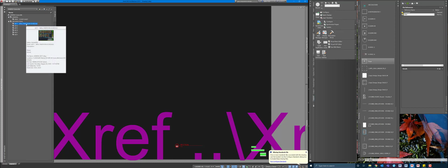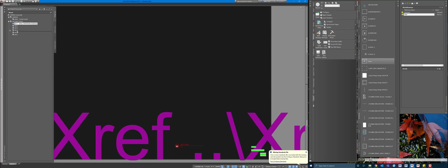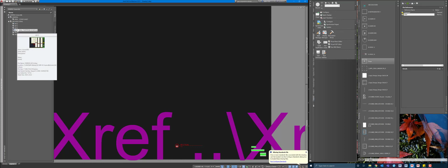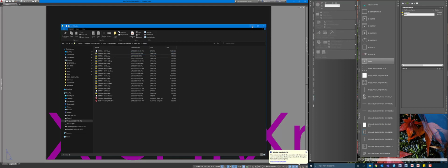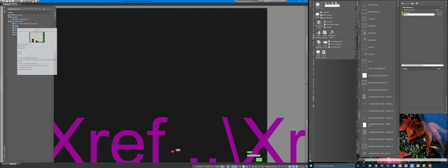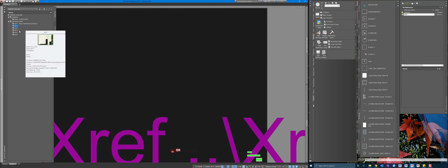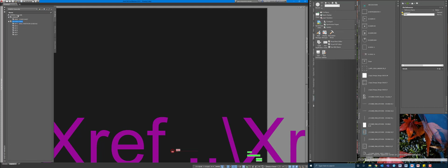Now, okay, going back to this, as part of sheet sets, you can click and drag. So again, if you just want to reorganize the order of your sheet sets, it's very easy to. Alright, renaming, renumbering, reorganizing sheets within sheet sets, moving around, you just drag and drop. It's fairly straightforward. Printing, you can hold down Control and select a series of sheets, or you can select whole disciplines, or you can select a series of disciplines.